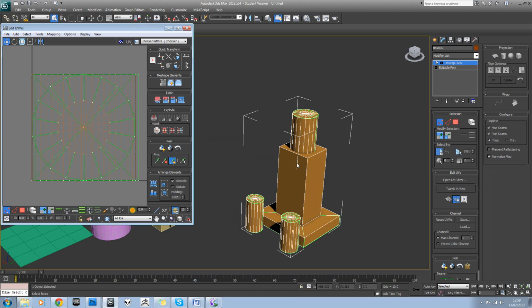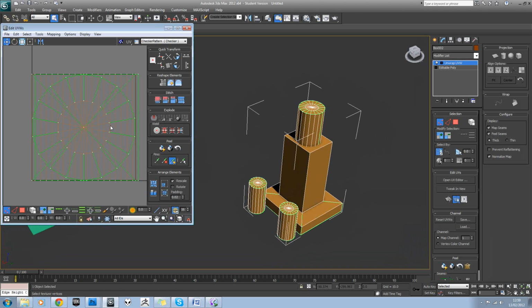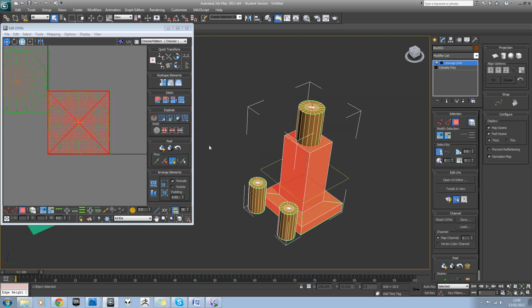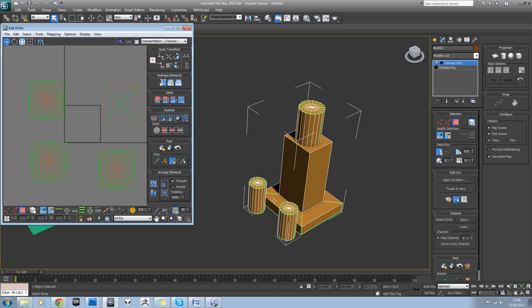and turn off the texture preview, you'll see that by default everything is kind of overlaid on each other, so you're often presented with this confusing window that can really throw people off. And this is when it's best to use your viewport rather than your window to start with. So if we go to polygon mode and select by element, and then we'll just select each component in our scene and just drag them out. Okay.